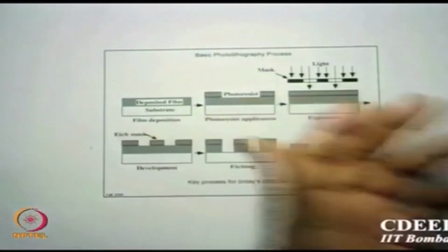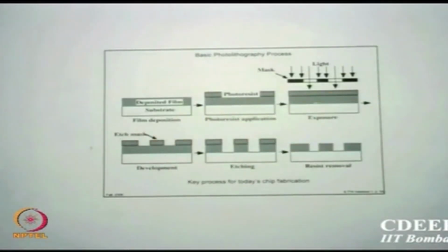The contrast to this is a negative photoresist, which is initially open, that is, a soft resist. Whenever light shines on it, it becomes hard, that means cross-linked and therefore unetchable. So the same mask with a different resist can do two jobs. Is that point clear?